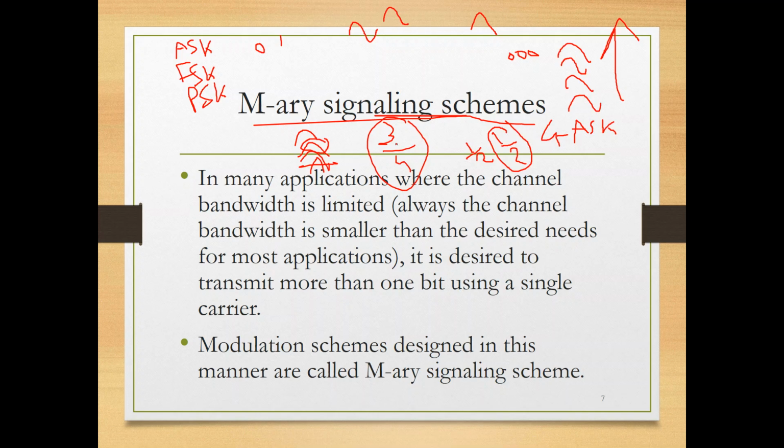Tell me, okay, don't fool me. I am very careful here. When you increase the number of levels, you increase the throughput, you increase the spectral efficiency, but there is a price you pay. You increase the complexity of the receiver, and the possibility of error increases. And if I tell you, convince me, you just explain these things that I just explained. You tell him logic.